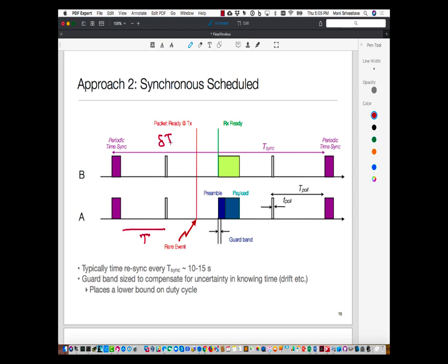For example, ordinary crystal oscillators that are used in our electronics, versus so-called temperature compensated crystals, which correct for temperature errors. And then there is the next category called oven controlled crystal oscillators, which literally have a little oven in the package, which keeps the crystal at a stable temperature.